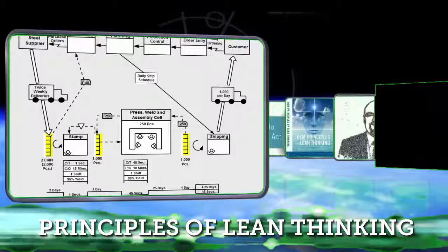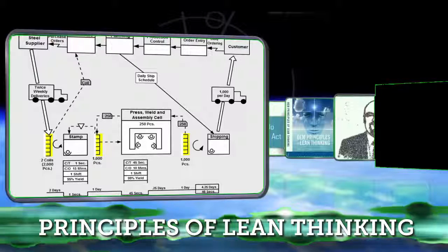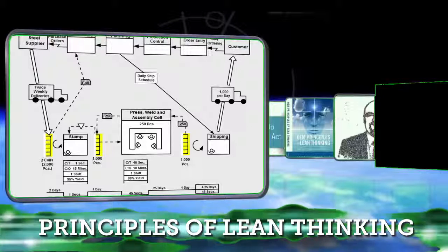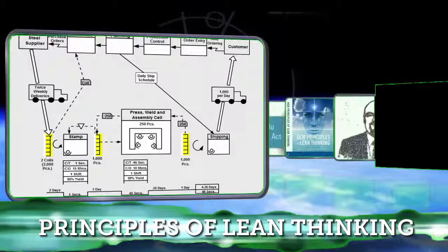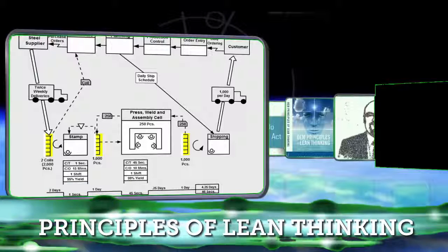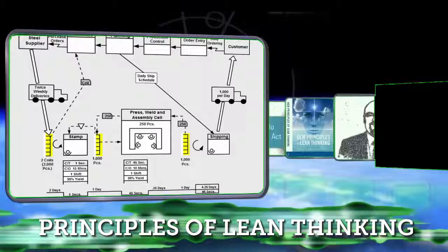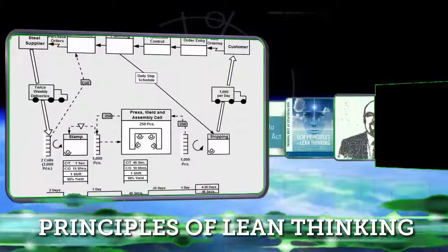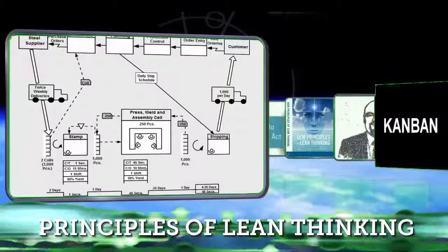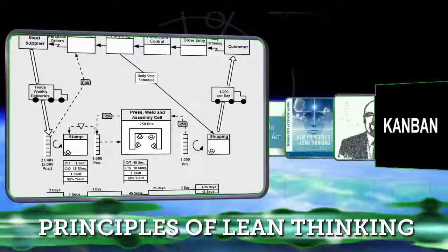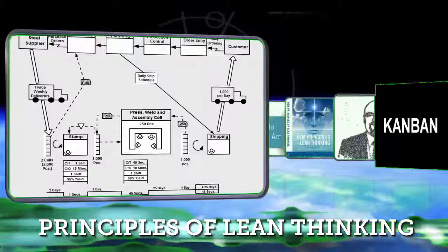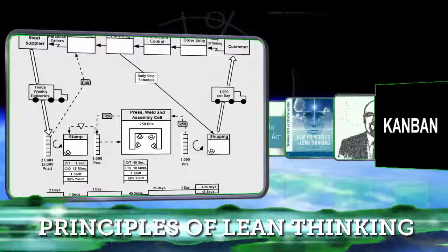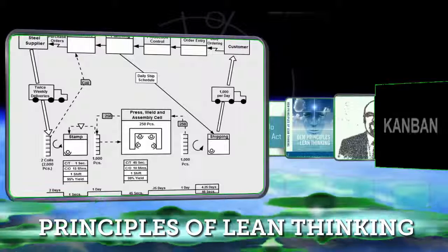With a pull system, a downstream operation or customer process withdraws the items it needs from a supermarket, and the supplying process produces to replenish what was withdrawn. In order to achieve this, a Kanban or signal is used that gives instruction for the production or the conveyance of items in the pull system.